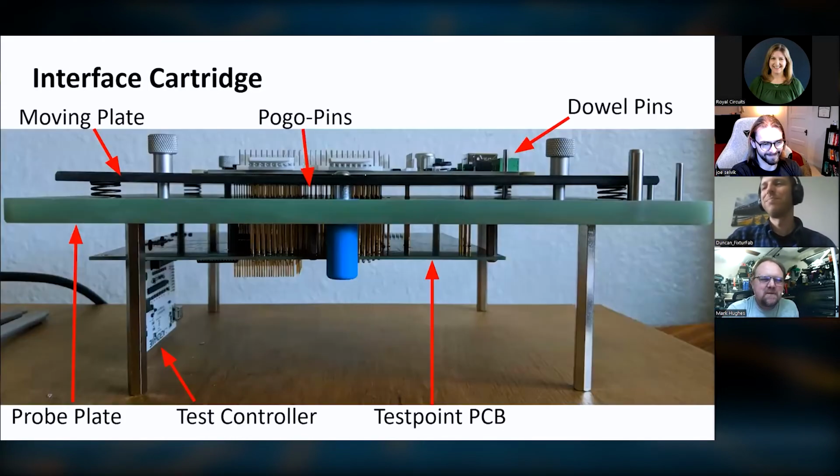Hey, so if I do a tooling hole, I'm assuming you guys have around 3mm dowel pins, somewhere in that range. Yep, our go-to is 3mm or 1/8 inch. Like an M3 hole, the clearance hole is what, 3.2 millimeters, I think, in diameter. And we have varying sizes, like 1/8 inch, 2mm, 2.5mm, 3mm. We'll just choose whatever is closest to what you have.